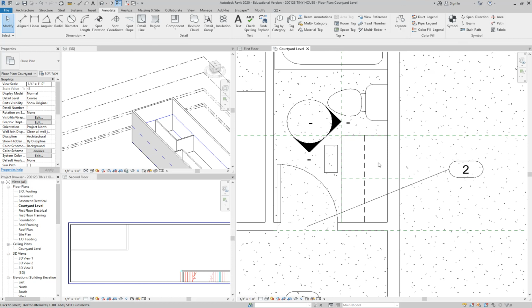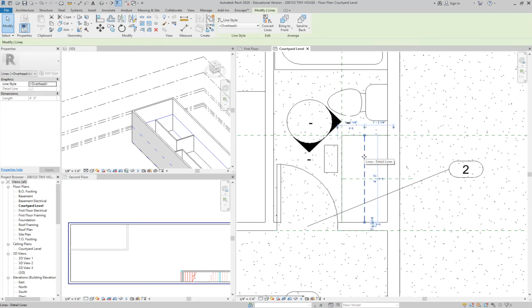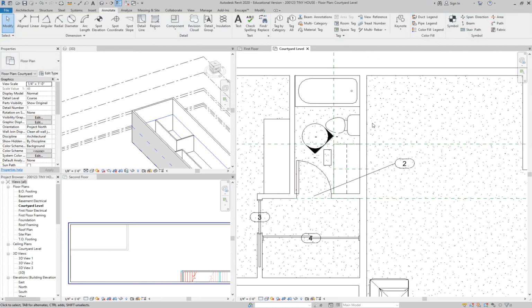The same thing applies when you're slicing through the kitchen for an elevation and slicing through the sides of cabinets. You would just draw an X and change that line type. And if it's showing too much detail, you could even do a detail region to box around the side of your cabinet if you wanted to. I don't know what the cabinet section looks like, so I drew all my cabinets.